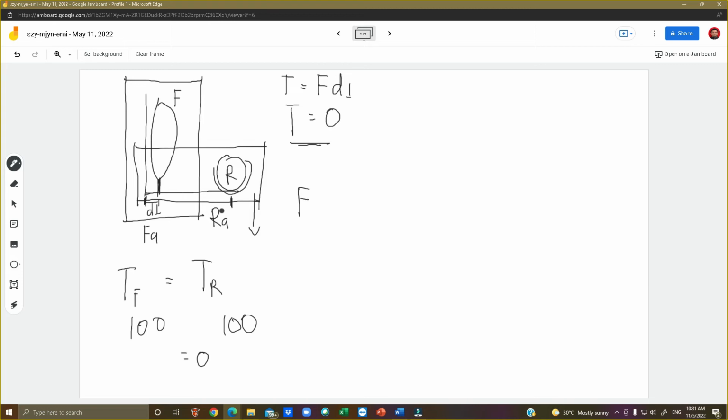So now let's try. Let's say this resistance is 20 Newton. And the distance between the resistance and the axis of rotation is 38 cm. Kita assume lah panjang tangan kita ni 38. Okay, saya keluarkan kat sini. We have R equals to 20 Newton. We have RA equals to 0.38 meter. Always turn our distance to meter.